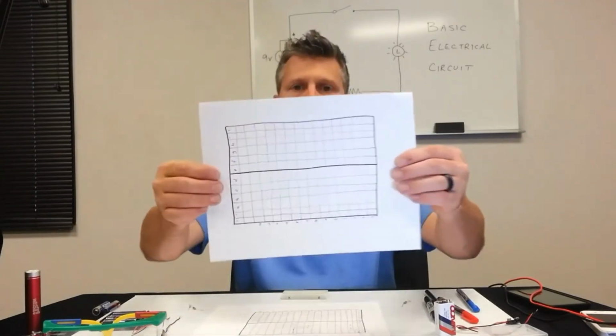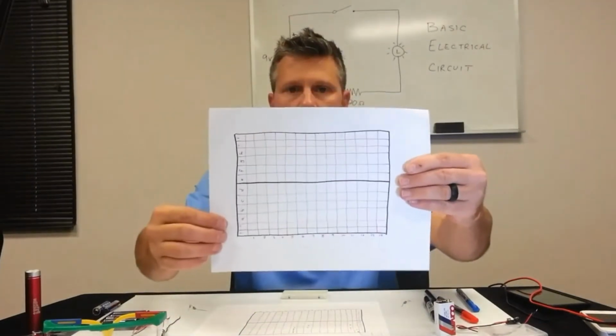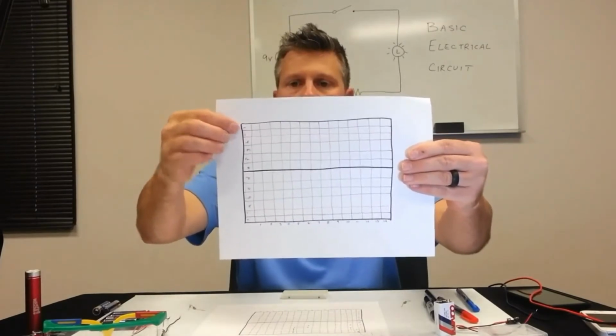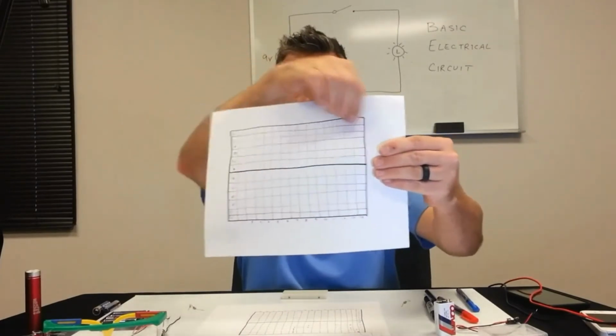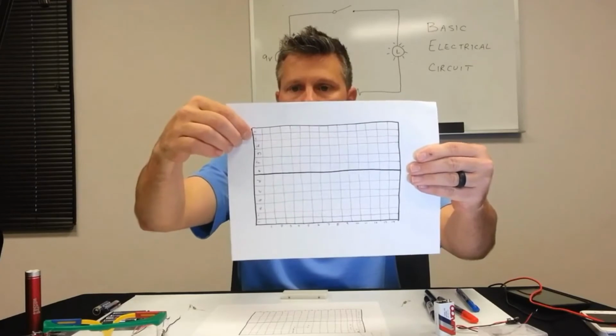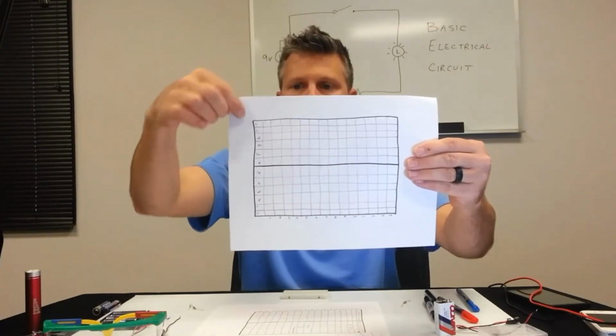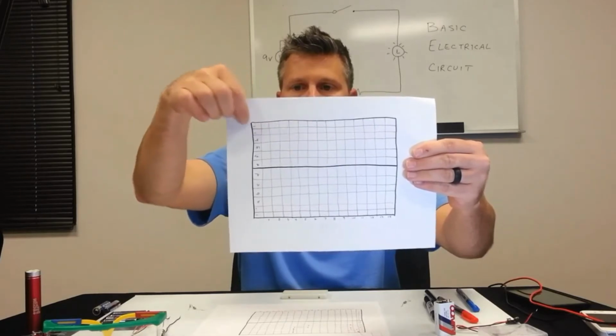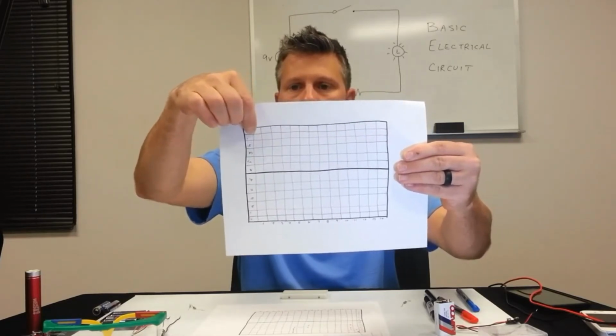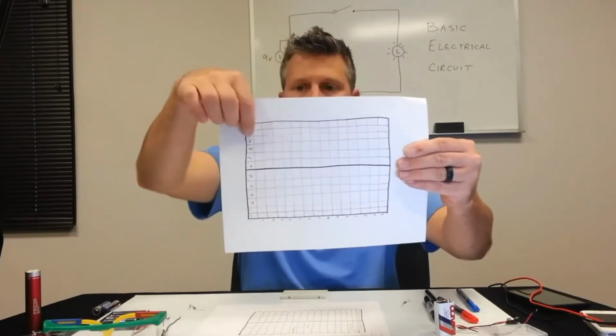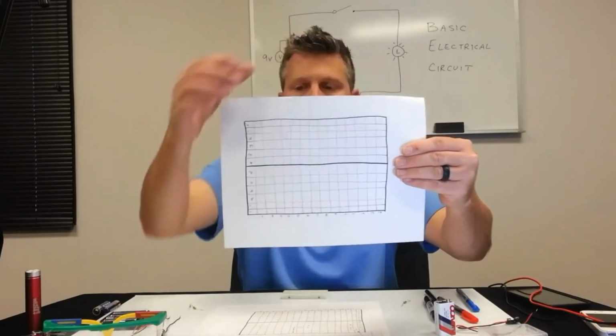This is a diagram of what a breadboard looks like. These two top rails, they go horizontal. So this is where I'm going to put my power. I have my negative and I have my positive, and as soon as I take power and jump it right into the breadboard, this whole rail will be negative, and then this whole rail will be positive.